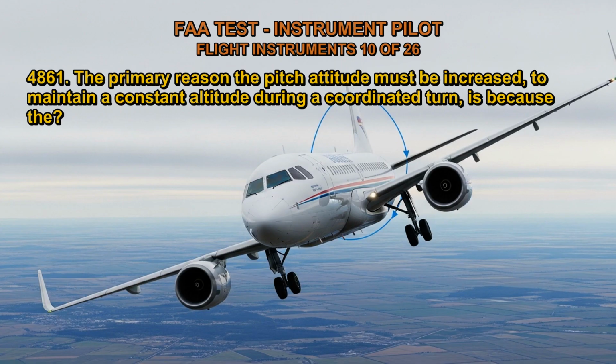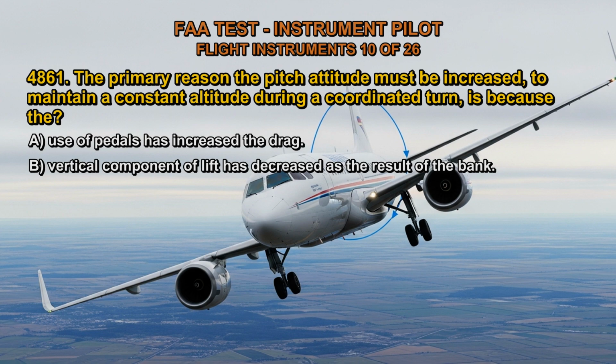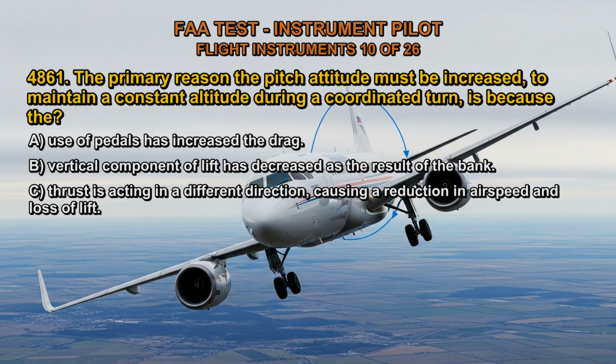4861. The primary reason the pitch attitude must be increased to maintain a constant altitude during a coordinated turn is because the A. Use of pedals has increased the drag. B. Vertical component of lift has decreased as the result of the bank. C. Thrust is acting in a different direction, causing a reduction in airspeed and loss of lift.